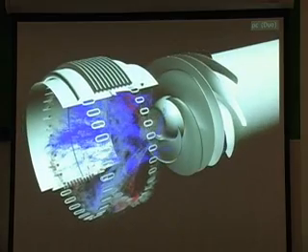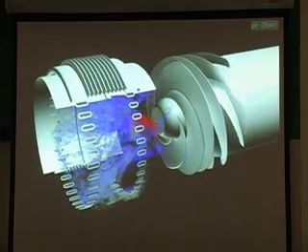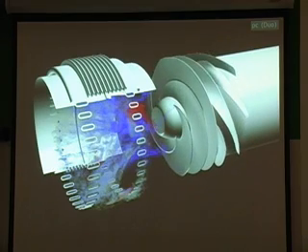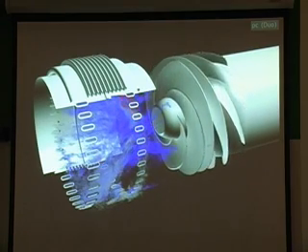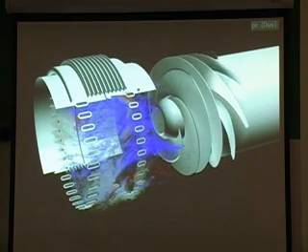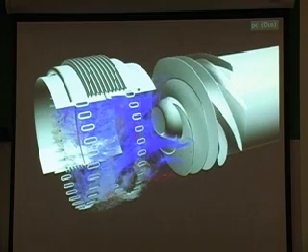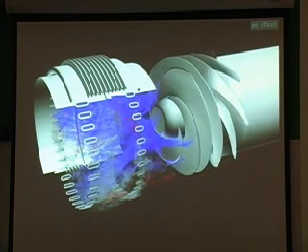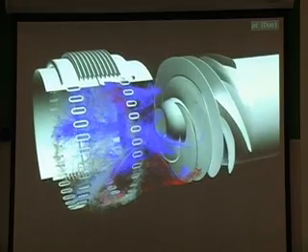And in general terms what's happening is that the flow has a lot of momentum and it's actually kind of bouncing back off the outsides of the blades. You can see this reverse flow in these pods around the outside. And what that gives rise to is a kind of back and forth motion and a resultant pressure fluctuation around these holes. And that was fatiguing the metal. And in some cases that was even leading to cracks.